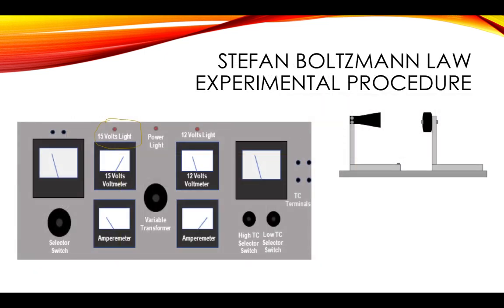For the Stefan-Boltzmann part of the experiment, the selector switch in the control panel was adjusted to 7, and the low TC selector switch was moved to 12. A black matte square aluminum plate was installed in the heater and aligned with a thermopile aperture. The heater was then moved 10 inches away from the thermopile and placed in the 0-degree configuration. The variable transformer was adjusted to supply 50 volts to the heater, causing the 15-volt indicator light to turn on. When the temperature readings in the pyrometer were stable, the values for millivolts were recorded. Pyrometer temperature and ambient temperature were collected. The same procedure was performed, adjusting the variable transformer to 60 volts and 70 volts.